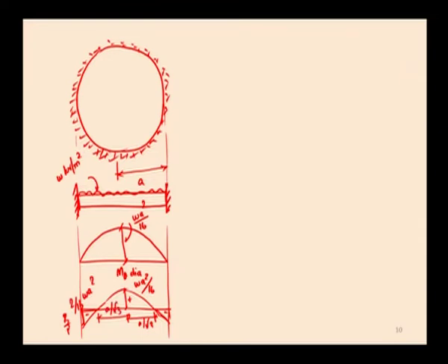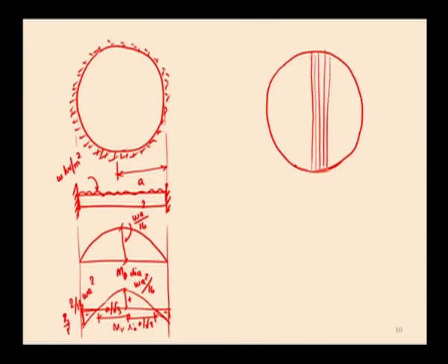And how to provide the reinforcement to resist this moment? This is the circumferential moment diagram, and this is the M r diagram, the radial moment diagram. First, to resist the radial as well as the circumferential moment at the center, the reinforcement has to be provided along both directions in the form of a mesh at the bottom. This is the reinforcement at the bottom.